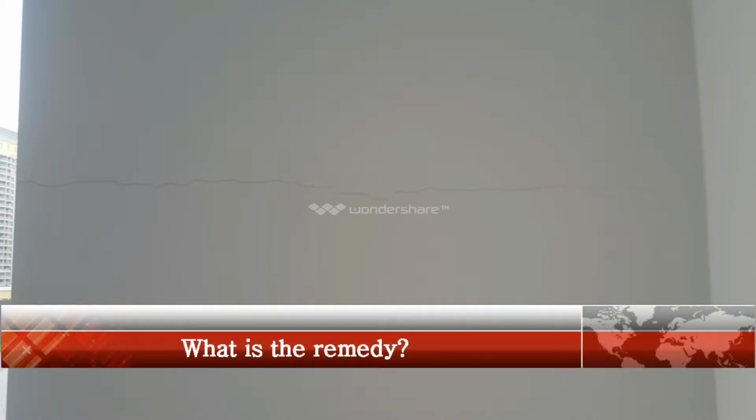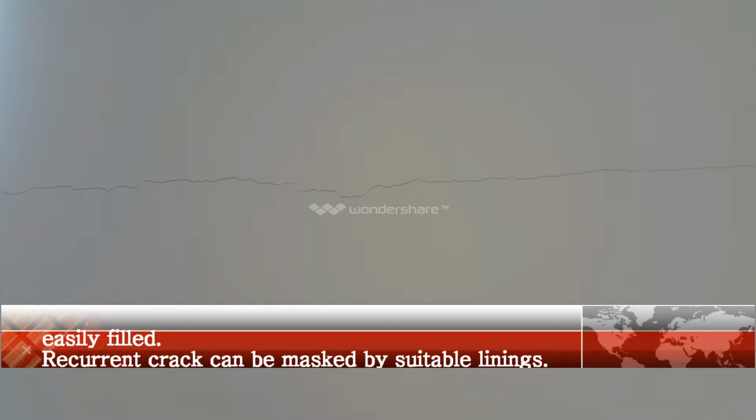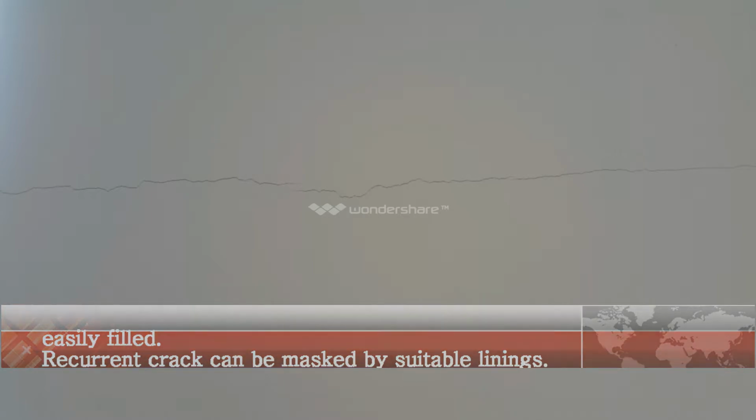The remedy for the slight crack, which appears here in this video, is that it can be easily filled, and a recurrent crack can be masked by suitable linings. Cracks are not necessarily visible externally. Some external repointing may be required to ensure weather tightness. Doors and windows may stick and require easing and adjusting.